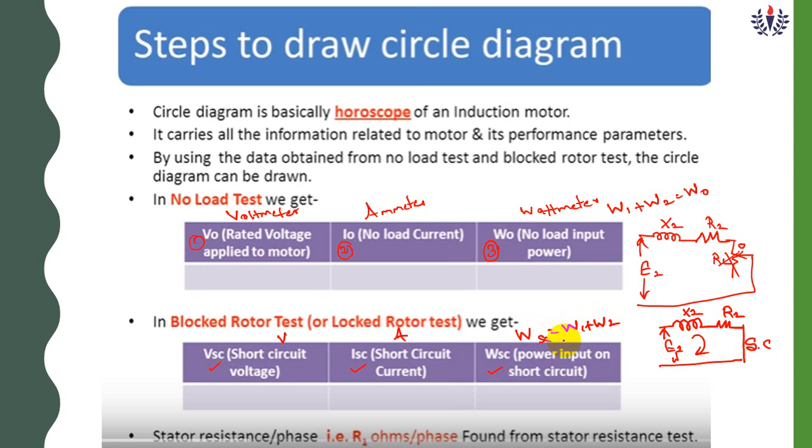Any doubt? The first step is to conduct the no load test, and the next is the blocked rotor test.